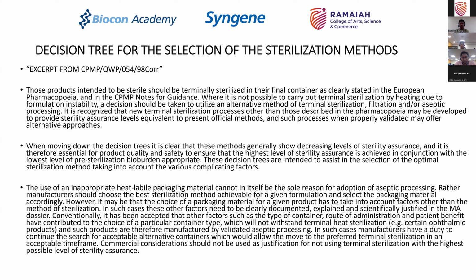One could be the compounding vessels themselves, or if you are using a filter to filter the solution into the holding tank, therefore using filter sterilization as one of the techniques, then the compounding vessels may not become as important as the final holding vessel, because you have finished the formulation, you are then filtering it through a sterile filter into a tank, from where it is then fed to the filling machine, where it goes into the individual containers.